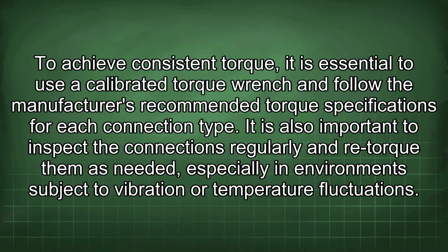To achieve consistent torque, it is essential to use a calibrated torque wrench and follow the manufacturer's recommended torque specifications for each connection type. It is also important to inspect the connections regularly and retorque them as needed, especially in environments subject to vibration or temperature fluctuations.